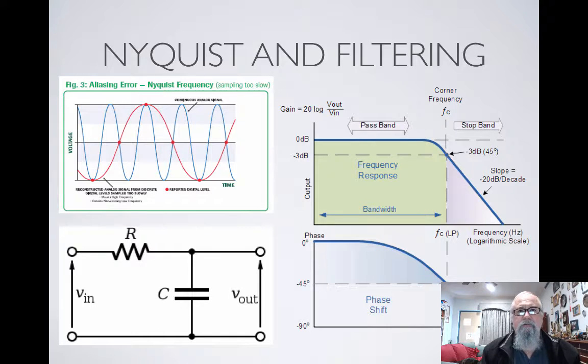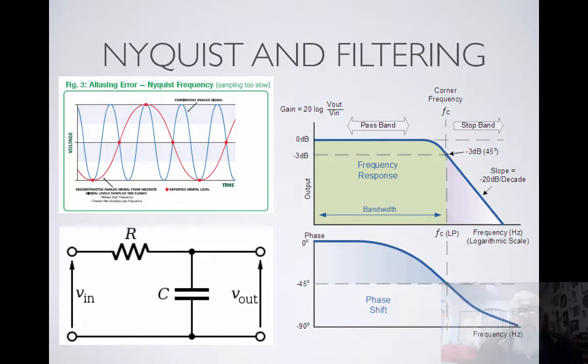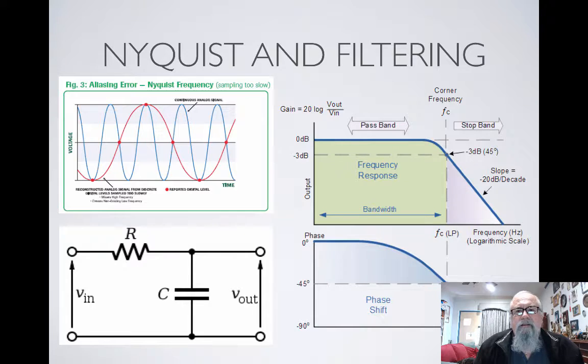In reality, it doesn't work like this, of course. What we need to do is we set our cutoff frequency, or corner frequency as it's called, in our speech signal, 3600 Hertz, and that then trails off, depending on the type of filter we're using, until it becomes a negligible signal. That signal is normally at the -3 dB point of the incoming signal, which is termed our half power point. And at our half power point, that is where we define our bandwidth. The signal would continue to come through, but at a much attenuated rate. This also causes a phase shift, which we're not going to worry too much about in here, but it is something that is important as you start to design more complex filters.